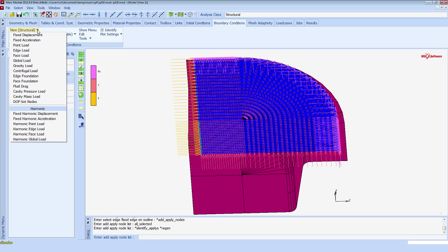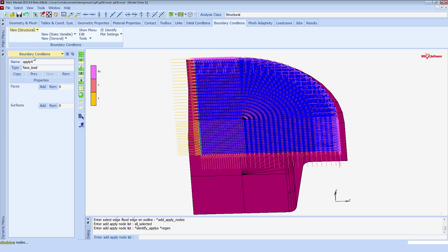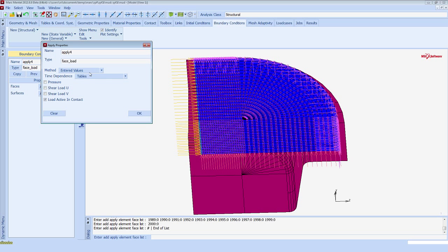There is one more boundary condition, a very important one, which is the pressure. We want to apply pressure on the sheet. So for that, I'm going to select faces, all the faces here, and you see that. So we have all the faces selected. It is showing up here, but you don't see the arrows yet because I have not specified any specific value over here. And once I go into properties, I'm going to use superplasticity control.